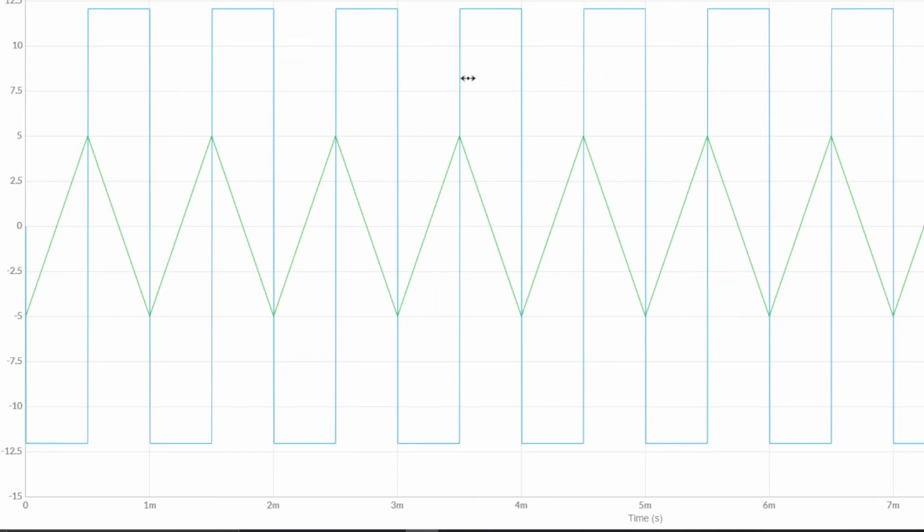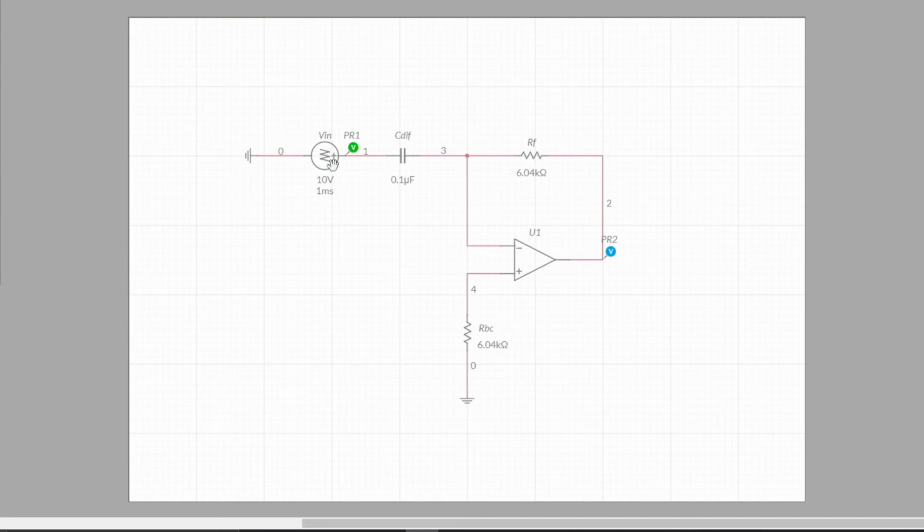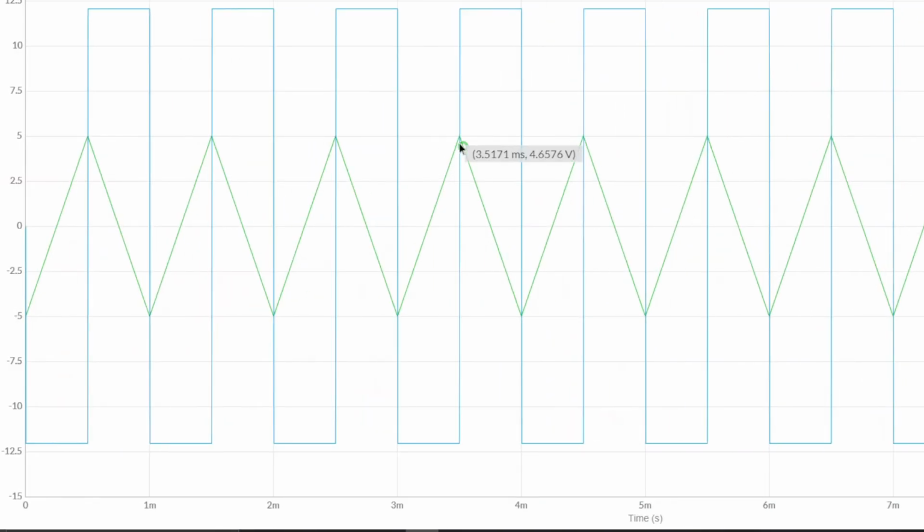It took us straight to the graph here. So we have a sawtooth triangle waveform going in. When we find the differential of that, we get a square wave, the complete opposite of our circuit before. As mentioned before, we have a 180-degree phase shift. It's going up here, down, down, up. And yes, as you can see, we can do mathematical functions with these amplifiers.